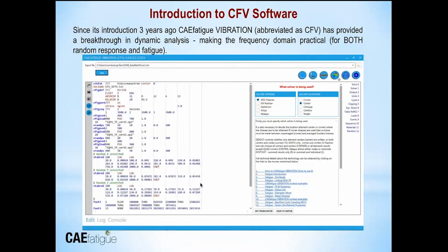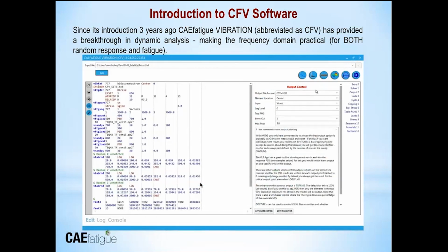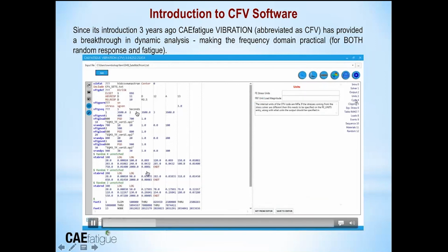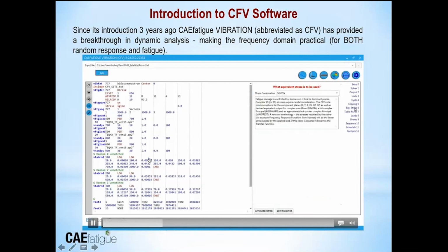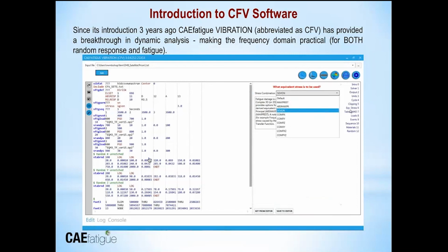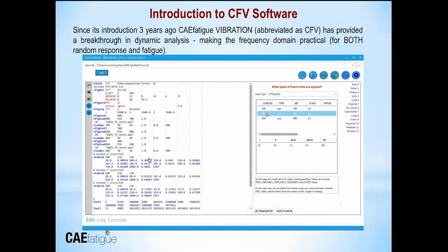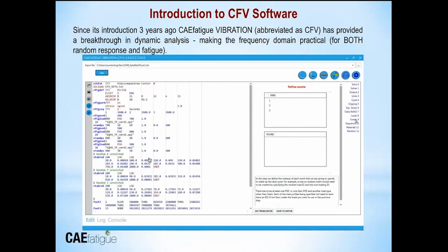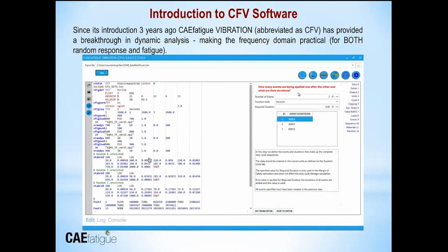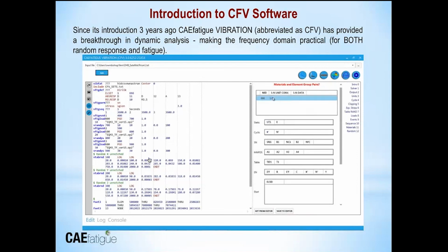The rest of these tabs are job setup tabs. So you have a choice. You can set up via a wizard, which is a kind of simplified GUI on the right, or you can set up your job in a Nastran format over here. Both are perfectly acceptable, and you can do one or the other, or in fact a mixture of both. So the wizard is really an either-or option for the user in terms of job setup. So this is how we set things up. We then have options for post-processing. I'm going to talk about that when I run one of the other live models.